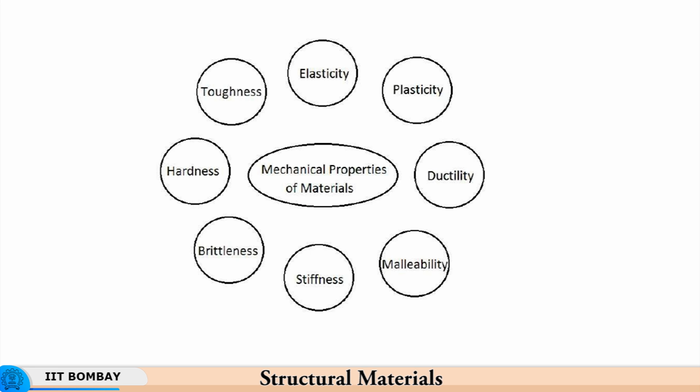Here there is no permanent change in shape, but there is a recovery of the original shape when the person gets up or when the loading is removed from the product. For any structural entity in use, the deflection, deformation and change in shape will be there, because you are loading everything to some extent, but it will come back to its original shape and size when the load is removed. So, that is what we call elasticity.